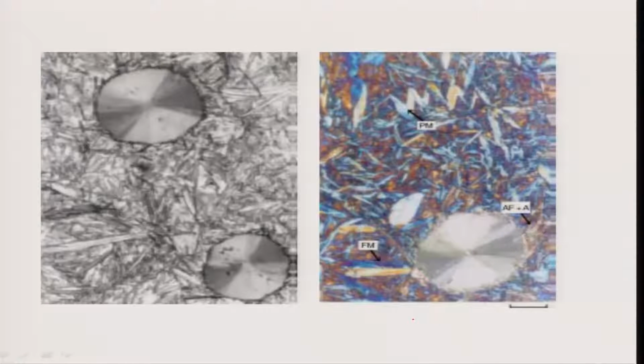Although I am telling you these nodules are spheres, they are not spheres. They actually have the shape of a thatched roof, as you see here. This is the peak of the roof, and these are the graphite parts joined like this. It is much clearer in this picture. You see, these are the graphite blobs. There are actually 1, 2, 3, 4 compartments, and this one is this. So, it is very clear this is not a sphere.